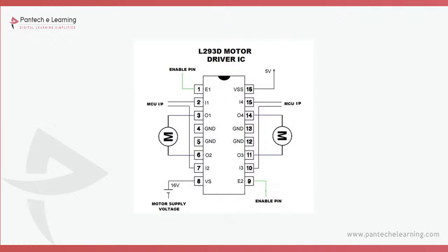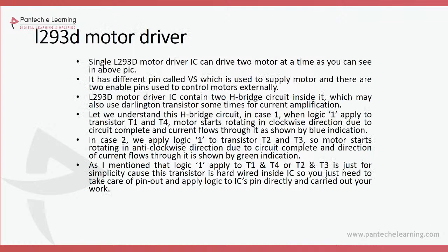After providing the 5 volt enable and the external 9 volt power supply, it will be able to obtain the rated speed. Based on the message received from the MATLAB software which we are using in our system, the controller decides a particular direction, and therefore the motor will energize with this supply. To get the rated speed of the motor, we have to provide at least 9 volt or 12 volt. For that reason only, we are using our motor driver.